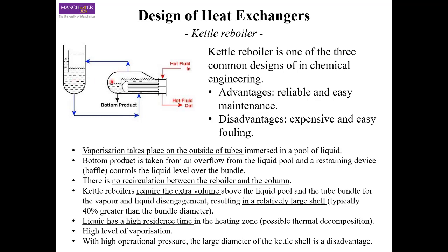In almost all distillation columns, you will see these kettle reboilers. And the reason they are called kettle reboilers is because they look or work on a similar principle as your boiling kettle, where you have this heating element that actually heats up the liquid here and then it vaporizes and then it enters the distillation column. So these kettle reboilers are very reliable and easy to maintain. As I said, you just have a heating element here, so in case there is a problem, you can remove this heating element and replace it with another set of tube bundle. So it is easy to maintain and quite reliable.